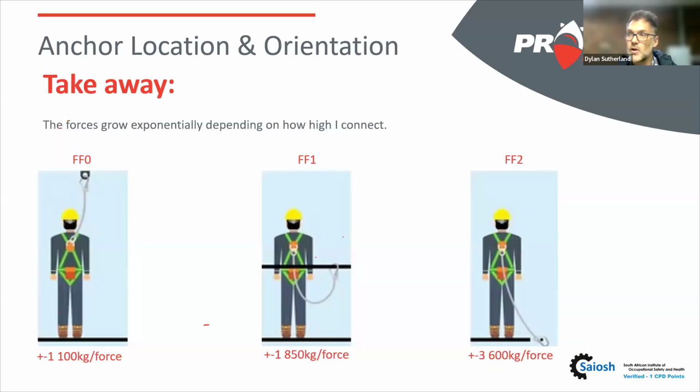Now, if we go to the takeaway of this, we just understand that connecting in these different orientations creates a significant change. From above my head, just over 1,000 kilograms, to at my feet, more than 3,500. So that's more than 3 times the forces. We need to be thinking about that when we are selecting where we put our anchor points.